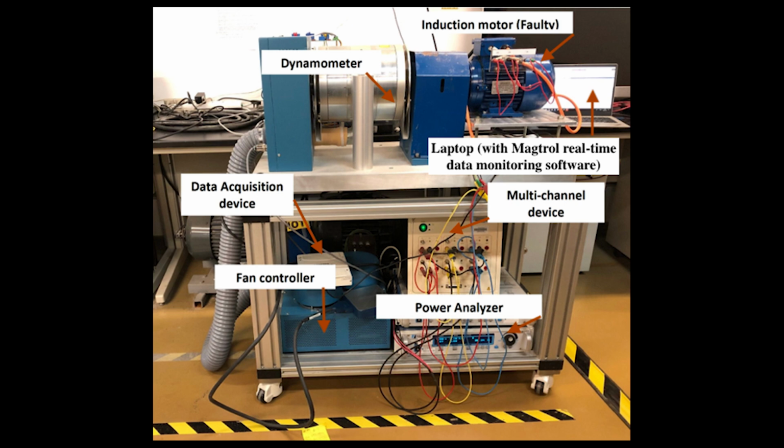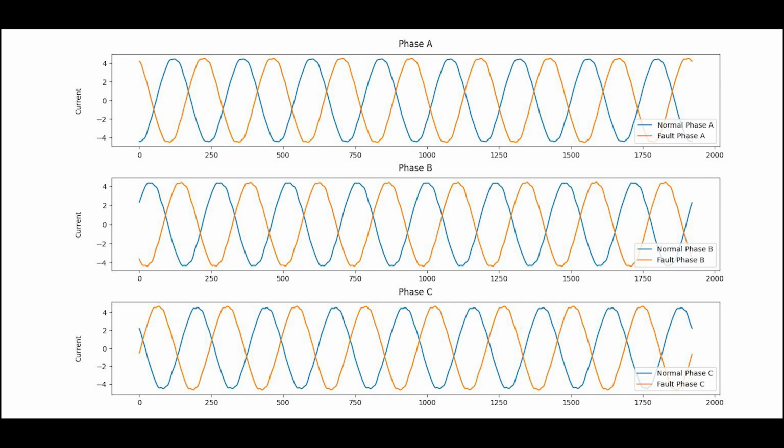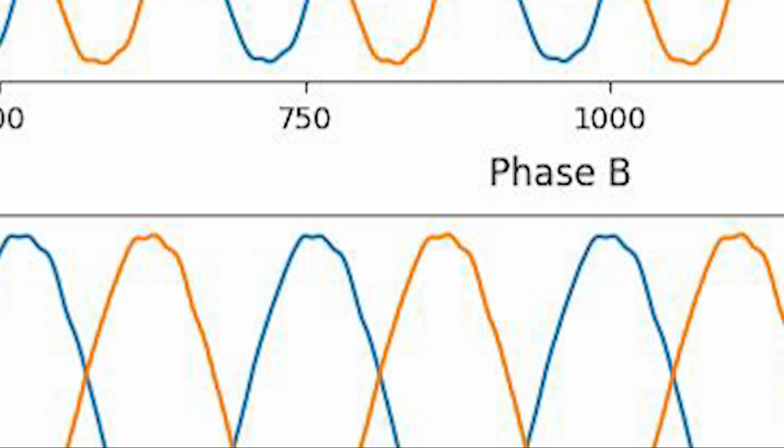Additionally, to observe current, a sensor is also attached to the induction motor to observe the current from time to time. Using current as a signature to measure any anomalies, we can see that the signal's sinusoidal waves don't match with each other. But that isn't important because we care about the slight discrepancies that are not visible to the human eye. We therefore refer to the peaks of the waves, and when we do, we see some distortions at almost every peak. This can lead to fault detection.